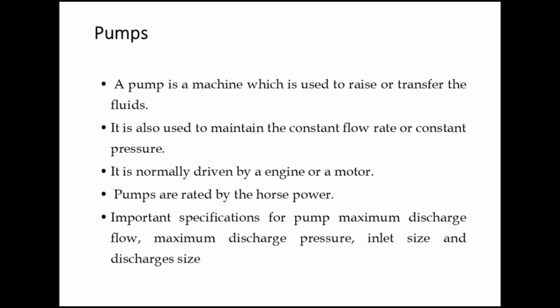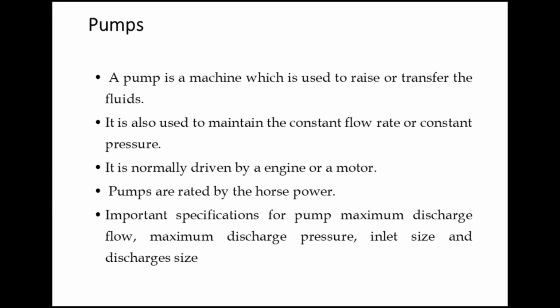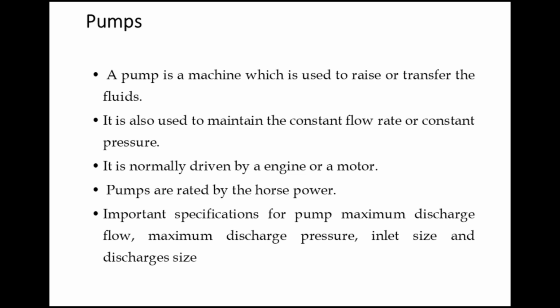Pumps. A pump is a machine which is used to raise or transfer fluids. It is also used to maintain a constant flow rate or constant pressure. It is normally driven by an engine or a motor. Pumps are rated by horsepower. Important specifications for a pump: maximum discharge flow, maximum discharge pressure, inlet size, and discharge size.